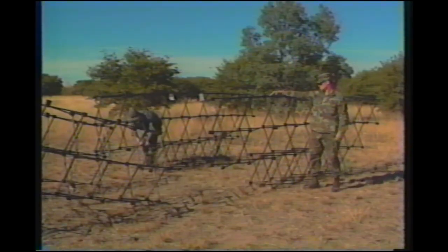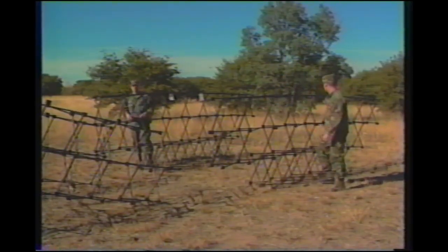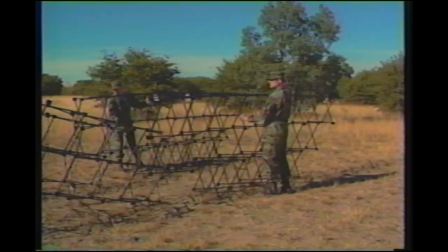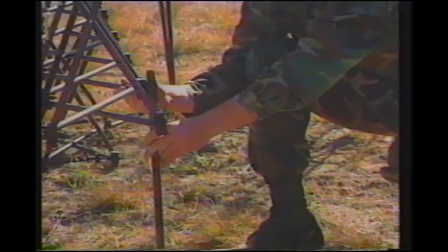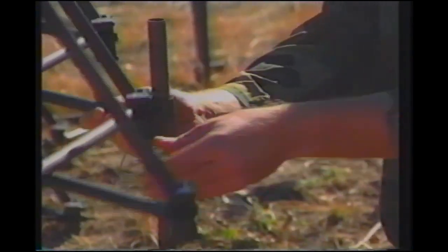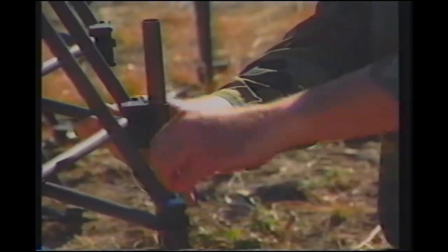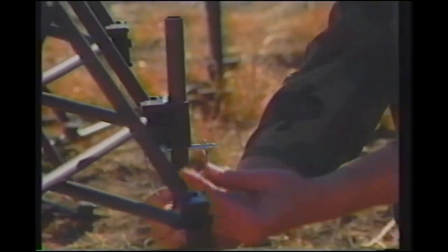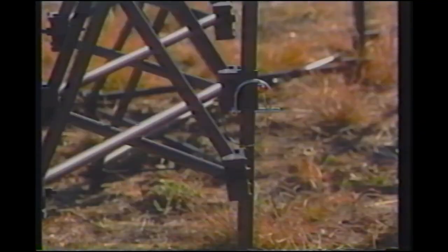Align the left and right side frame sections with the front frame section. Position the 2 short adjustable frame support legs into the frame collars on the rear inside corners of the front frame section. Level the front frame and slide the safety snap pin through the support leg below the frame collar. Secure it with the spring wire.